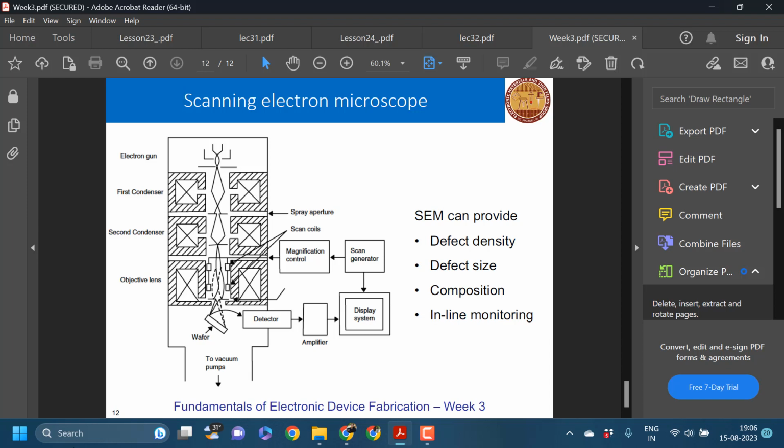Electrical measurements, first and foremost thing we will be studying will be the resistivity. Once that is done, we can go for IV characterizations. Next, when it comes to physical measurements, that is usually for finding out whether the dimensions are appropriate or not. For this process, we will be using white light interferometry, ellipsometry, profilometry, etc. And finally, for defect characterization, we will be using techniques like optical microscope, scanning electron microscope, and transmission electron microscope. So is that clear till now?